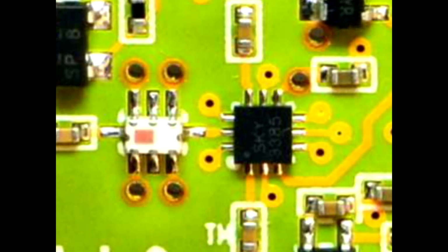I filter as much as I can of unwanted frequencies with one component that I found using my favorite filter design tool. And then I have this little structure here that allows you to provide DC power to the antenna port through an inductor. We'll talk about that in a little bit too. That's the entire RF section, all summed up here. So this is a lot more complicated, but it's still following all the same rules that I talked about earlier. They're the rules I follow for all my designs.